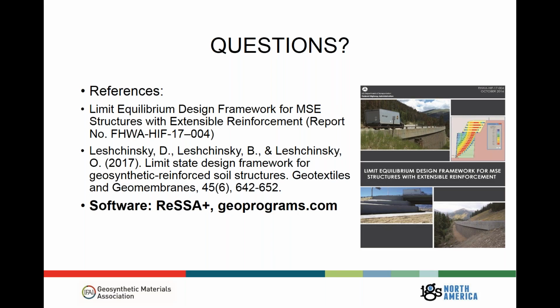When I've seen this problem addressed, it becomes a construction quality assurance issue, and having a qualified person on site to monitor construction, which I know is challenging in some wall design budgets. That's exactly right, John. It's usually very difficult to compact up near the face, and that can result in some problems down the road. Okay. Next question.